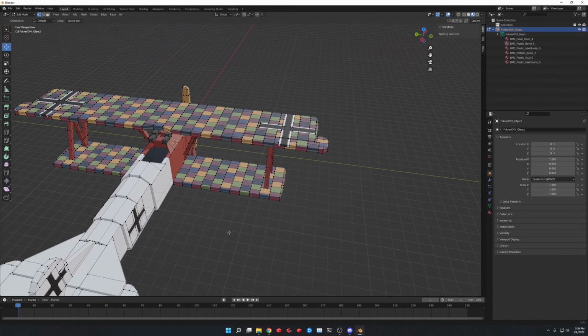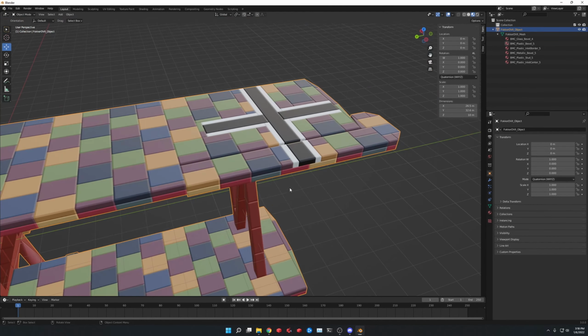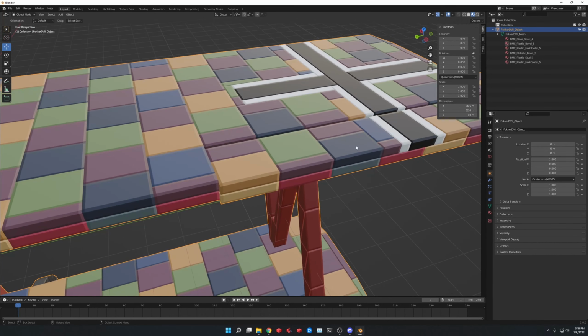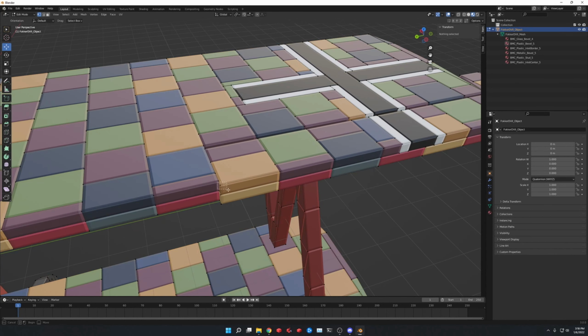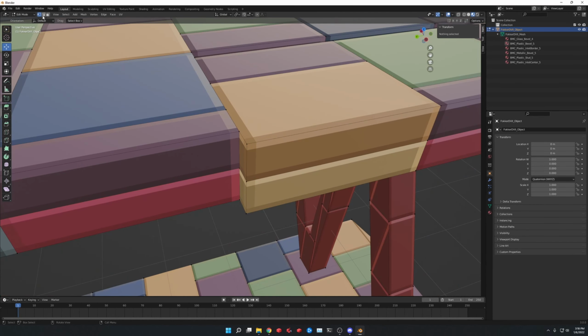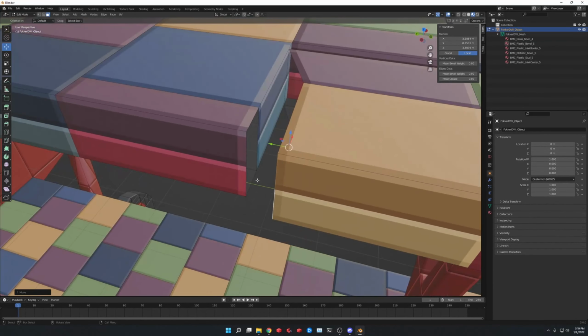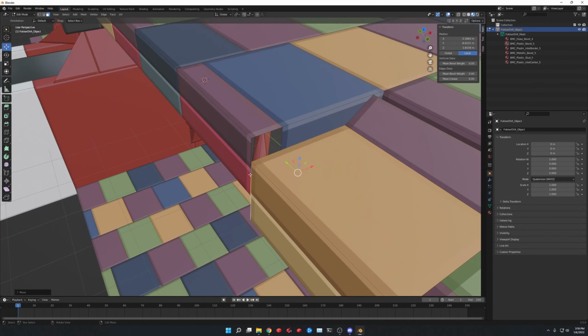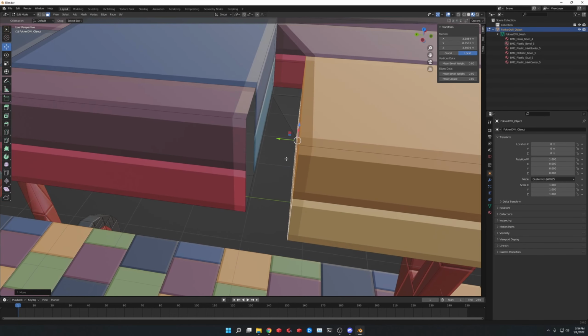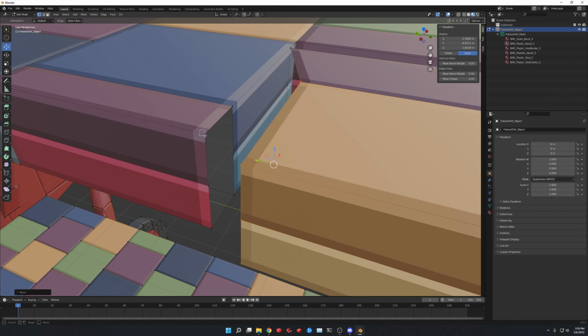But now that we figured that out, now we have to tackle our potential problem with the ailerons, because if we look closely around this area, and pull away these faces, we'll see that we are missing some faces here, and that's going to look bad when we rotate our ailerons and we just have a hole in the mesh. So we're going to fill in this hole.